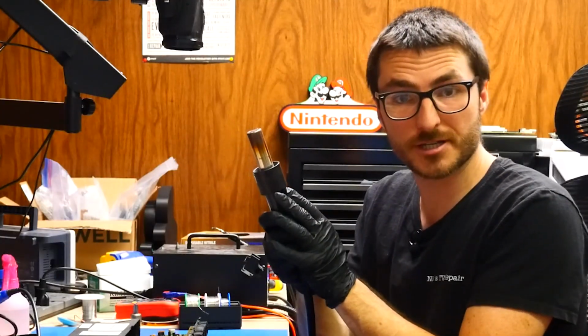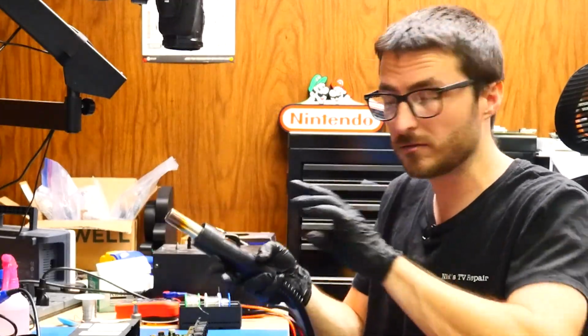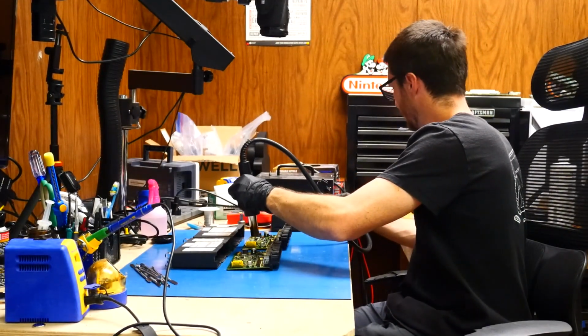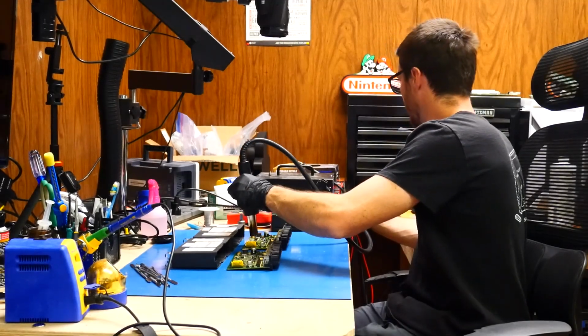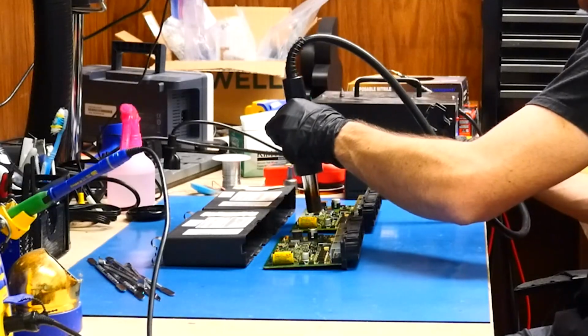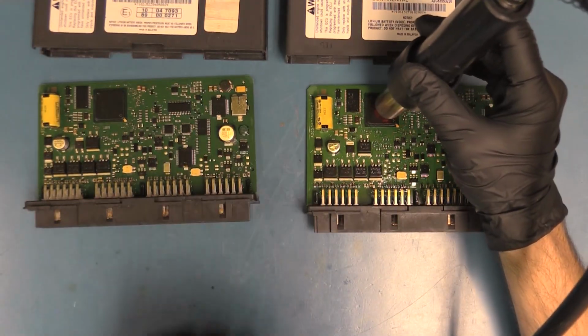Our quick diagnostic is going to be for us to heat up our processors, and we're going to be using a hot air station, but if you have a heat gun, that would work as well. So what we're going to do is turn it on. We're going to start with the CPC4 hardware fault and throttle issue over here, and I'm just heating that up for about 20 seconds or so. And I'm just heating up this processor here.